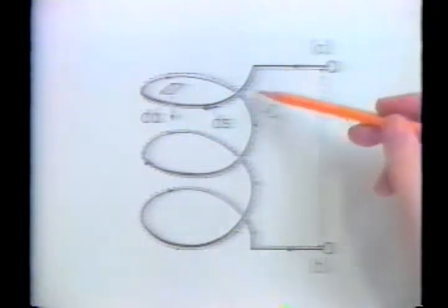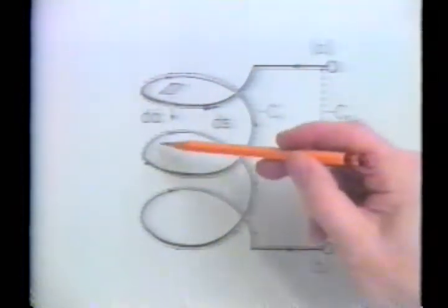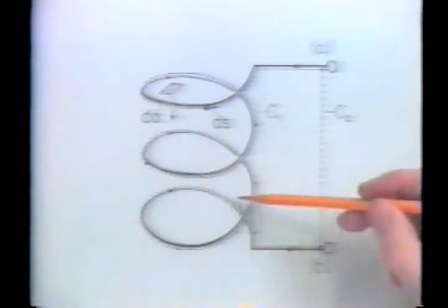If the terminal voltage is to be a uniquely defined quantity, independent of the layout of the connecting wires, the terminals at A and B of the coil must be in a region where the magnetic induction is negligible compared to that within the coil interior.